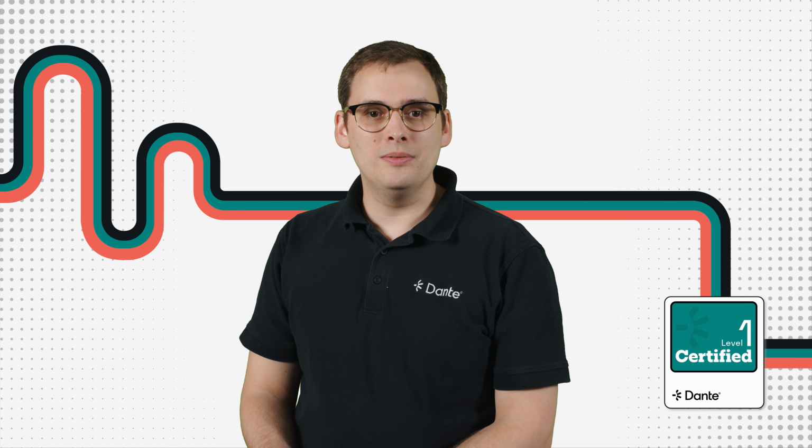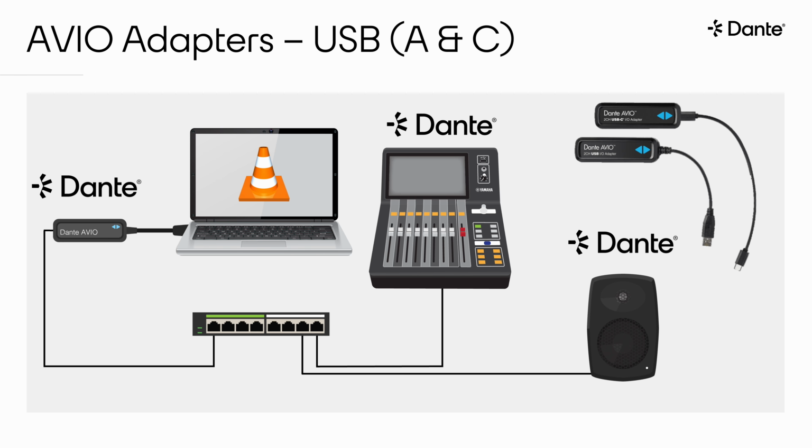Let's see an example. Here we've got a computer running a presentation with some music. This will be sent to a mixer, and that mixer will send its output signal to a Dante-enabled loudspeaker. As expected, this computer doesn't have any Dante software to send audio to the Dante network. By using a USB-C or USB-A AVIO adapter, the presenter can send their computer's audio to the Dante network without installing drivers or software.